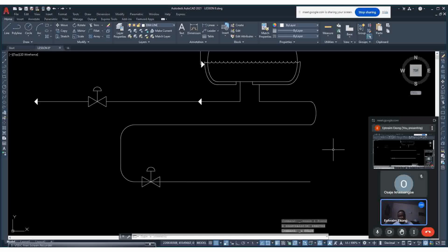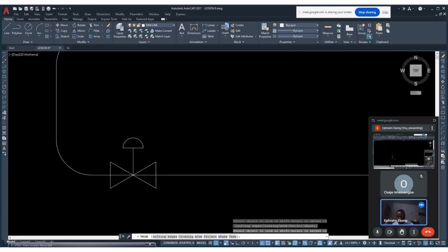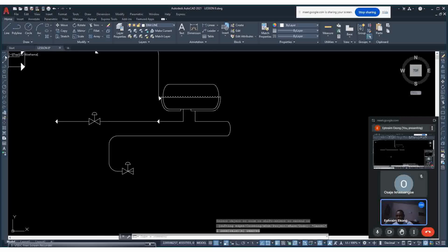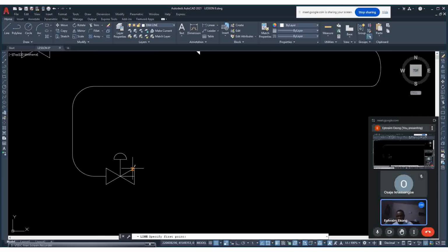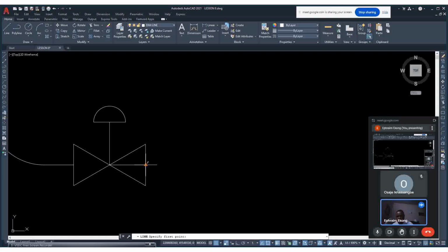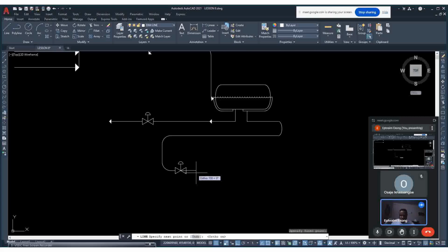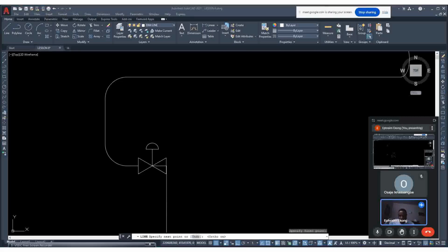Undo. You can trim. Go to trim. Enter and trim this off. Trim this off. Okay. So we want to achieve the midpoint. Go to line. This is the midpoint. That's why we did not trim it. Click on it and ensure your auto is on to have the snap points. So what next? Go to drawing.